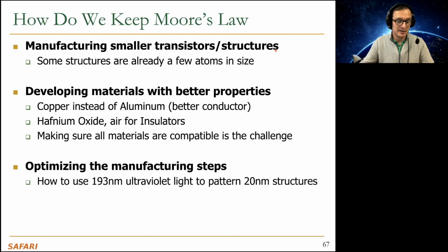So the manufacturing is actually very interesting. Basically, you use light technology, lithography, to pattern a particular pattern. So essentially, to etch the transistors on silicon, and that requires very high precision light structures, as well as high precision devices to pattern very small structures. And this says 20 nanometers. It's an old slide, but imagine doing this for 5 nanometers. You don't have much margin of error. You're trying to etch a 5 nanometer transistor, and if you make a mistake, it's gone, basically.